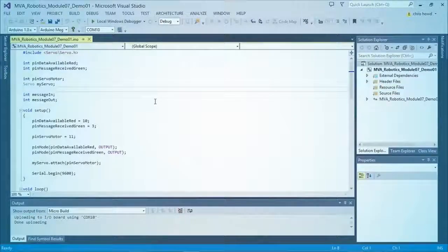That same software can be used for communicating. So we have our coordinator plugged into our PC, and we have our router connected to our Arduino board, and we are going to communicate using the software from XBee, from the coordinator on the PC to the router on the Arduino demo.